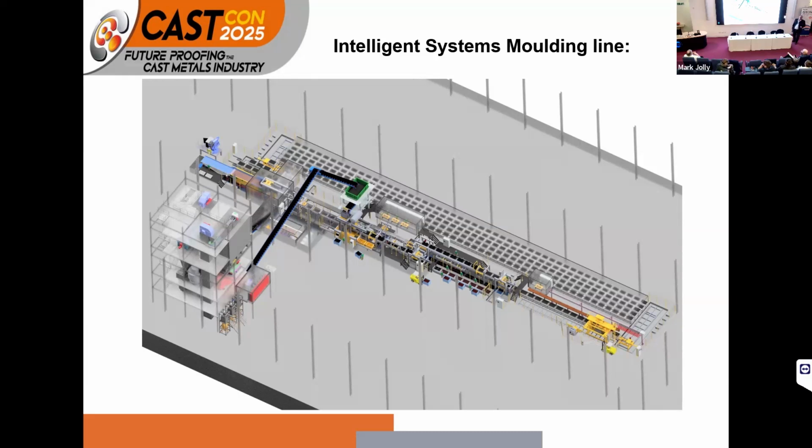Then vision control systems. There are different places to set a vision control system. One can be on the molding machine on the top, to see by contrast if you have any residual sand in the corners or whatever, which is not going out, and where there is a need to clean the pattern.